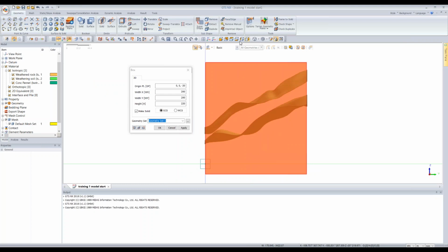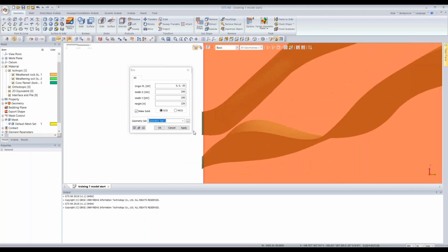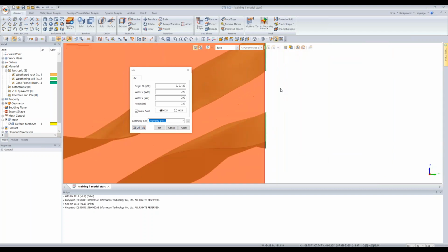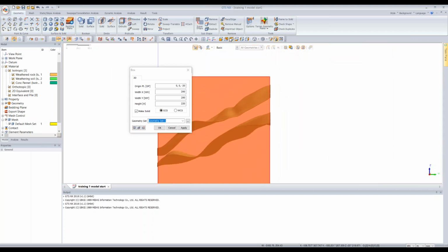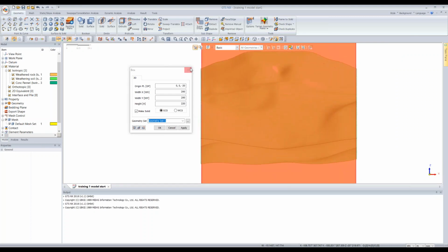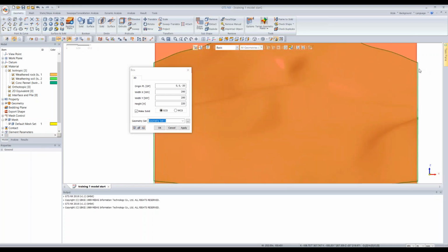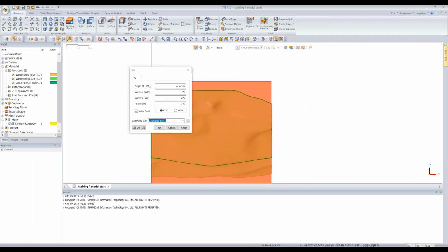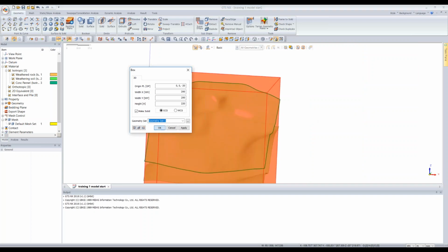Obviously, this is something that you plan ahead of time, but even if I go to the right view or the front view, I want to be able to see that my surface is completely coming through the cube, or else I will not be able to divide. So the last inspection would be the front inspection, and I can see on both sides that the surfaces do pass. If the surface doesn't cut through the solid entirely, if there's a part of the solid that's not being crossed by the surface, then the program will not be able to divide it.